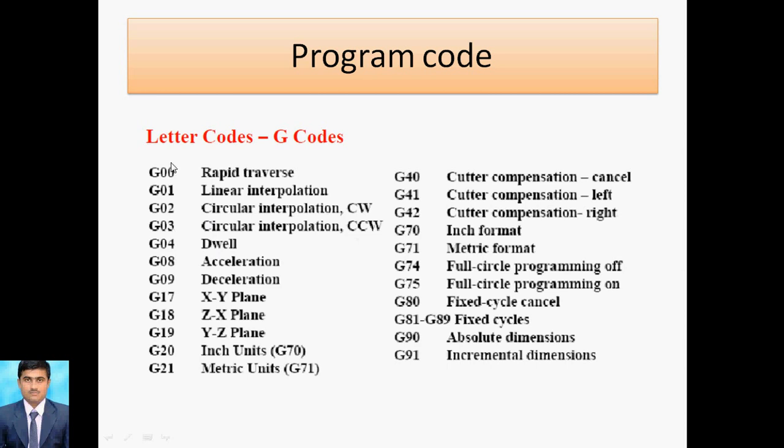Then G04 dwell, G08 acceleration, G09 deceleration, G17 that is XY plane, G18 that is ZX plane. Then G20 inch units, G21 metric units.